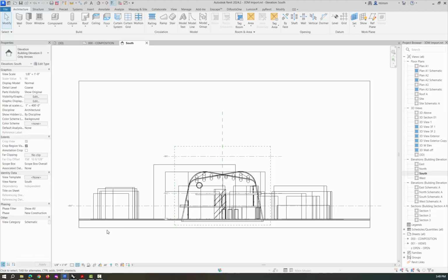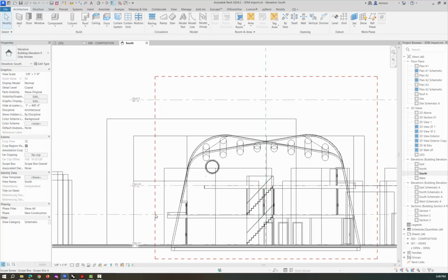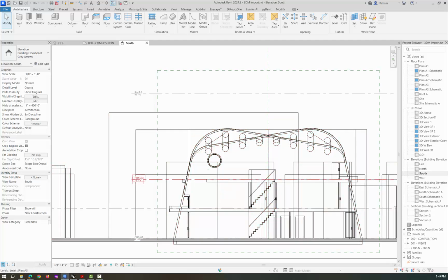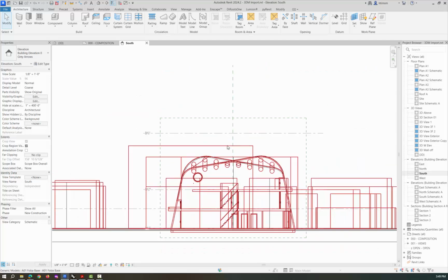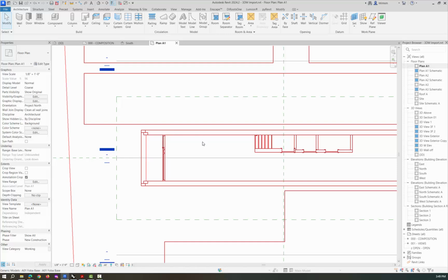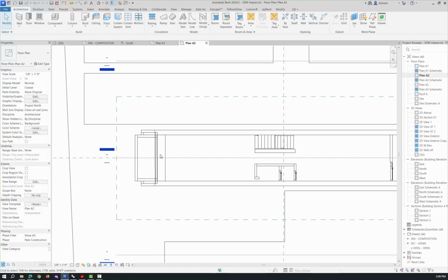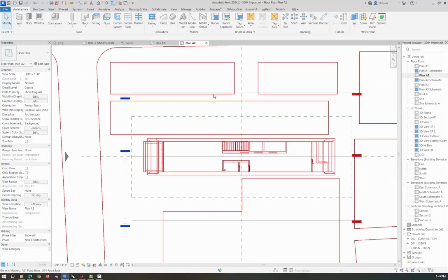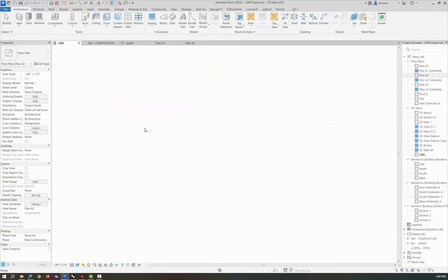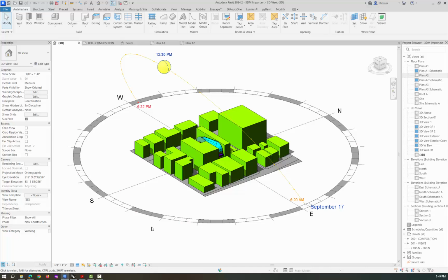So if I go to a wireframe, you can actually place these levels even with the floors, and it will then cut the sections based on those, right? So if I go to my plan A1, I'm looking at that section cut 4 feet above, and then plan A2 will be 4 feet above the second floor, and you can kind of see how all of that is working. So that's basically what we're going to do. And that's just to get you familiar with the environment. Again, it should be pretty straightforward.